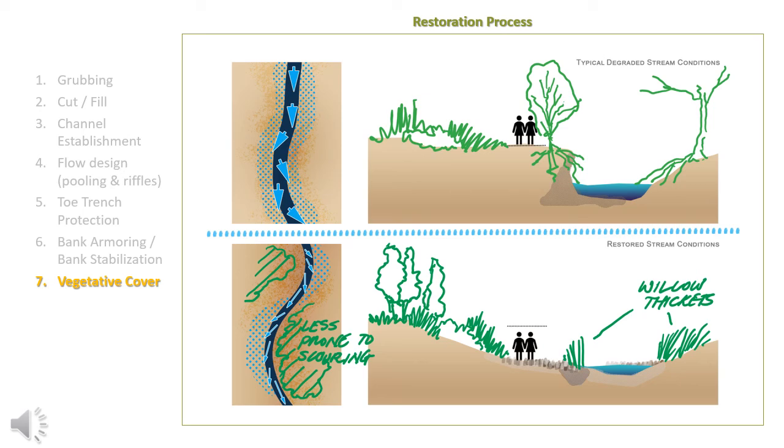what you're going to see is actually a move towards shrubs and willows, thickets, things that are going to send out a fibrous root system but are not going to be extremely large, being part of the mix right in and around the streams. Willows are a great example. Willow thickets can get up to be 10 or 15 feet tall. They'll grow very dense right around the stream corridor itself. It may limit the visibility of the stream corridor, but we can open it up in strategic places. This might be the right solution.